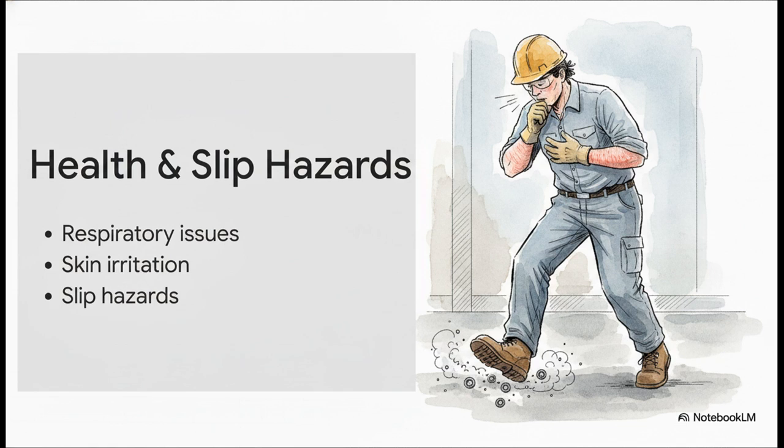But take a look at that third bullet point. Accumulated fine dirt on floors creates slippery surfaces. We always tend to think of water or oil causing slip and trip hazards, but actually a layer of fine dust acts like thousands of microscopic ball bearings on a smooth concrete floor. It's a major physical danger, yet we almost always overlook it.